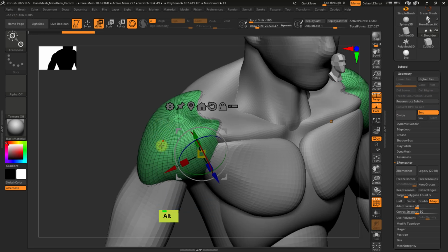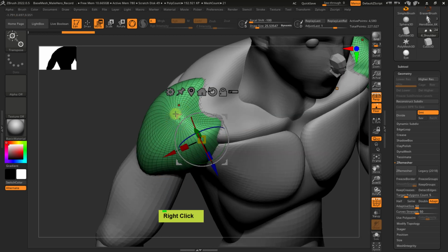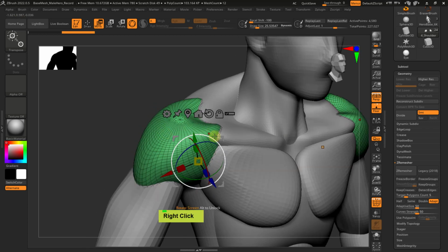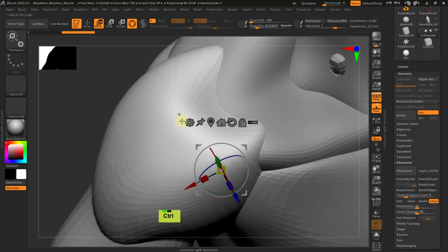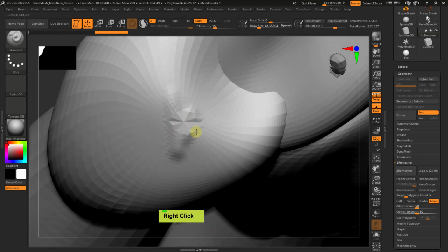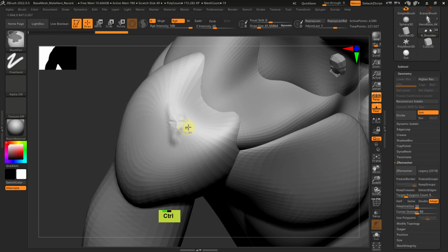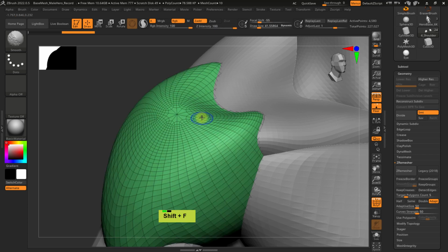And as you see, this is not a uniform mesh. So we have stretched out polygons here and there, but we have high density polygons there. And we are losing data basically, and it's unwanted complexity for file save and for speed of work. Also the brushes are not working consistently, because where you have details, it's okay, but here if you start sculpting, you will see that things are a little bit off. So let me just use the standard brush. I'm pulling on it, and as you see already, we have this weird form. So this is one of the reasons why we try to create a good solution that's sculptable.